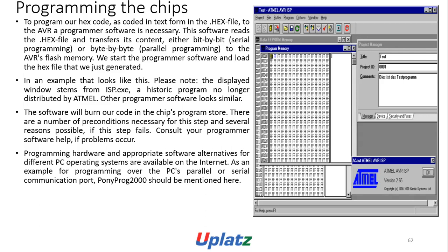The software will burn our code into the chip's program store. There are a number of preconditions necessary for this step and several reasons possible. If this step fails, consult your programmer software's help if problems occur. Programming hardware and appropriate software alternatives for different PC operating systems are available on the internet. As an example, for programming over the PC's parallel or serial communication port, PonyProg2000 should be mentioned here.